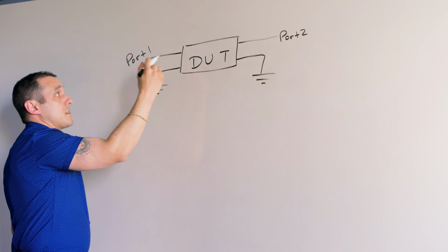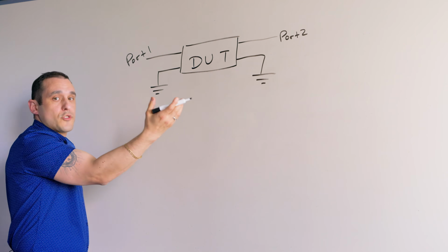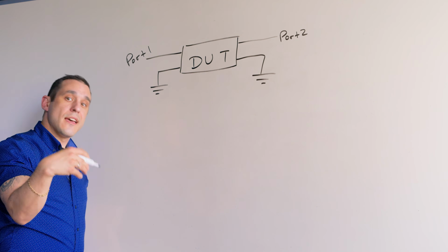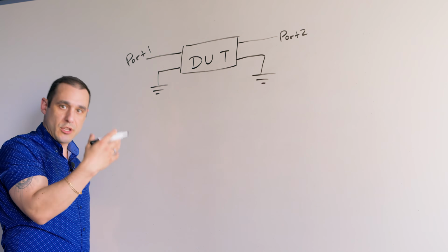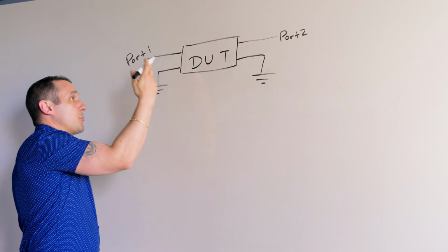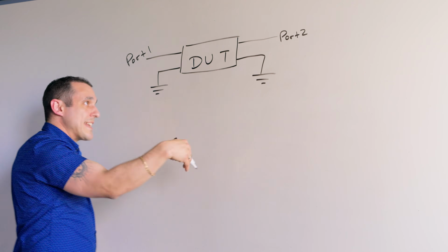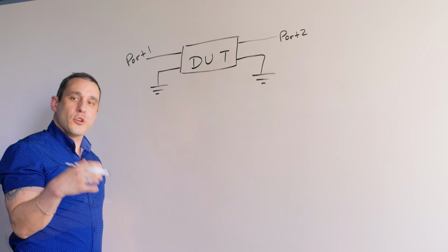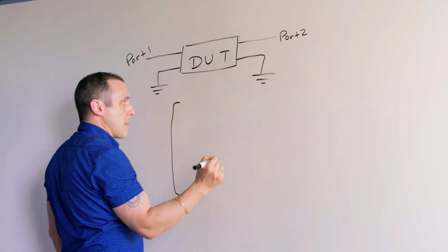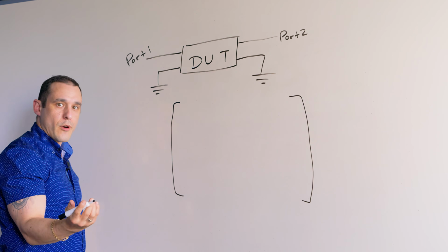The port in this case is basically a differential input. So we can input differential signal and we can get out some differential signal. But as I mentioned previously, in that example with inputting noise and signal and getting out the other mode, we can input differential signal but get out common mode signal, and vice versa. We can put in common mode signal and get out differential mode signal. To quantify all of this, we have a matrix, just like with the standard S-parameter formalism. But instead of a 2x2 matrix, we have a 4x4 matrix.